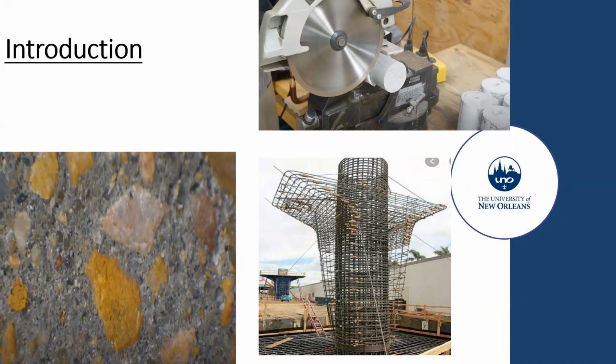Notice how cement paste fills the gaps between fine and coarse aggregates. It serves as a binder, holding the other ingredients together. You don't build the structure from pure cement, the way that you don't build furniture exclusively out of wood glue. Instead, we use cheaper filler materials, gravel and sand, to make up the bulk of concrete volume.